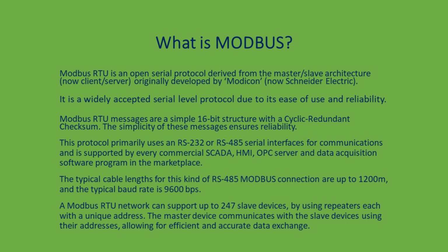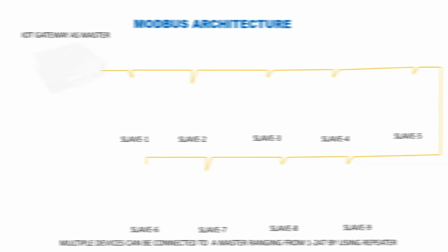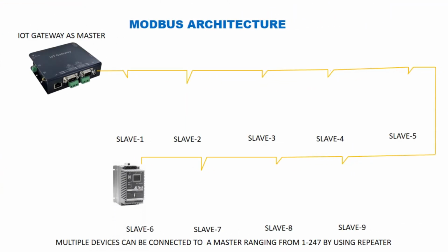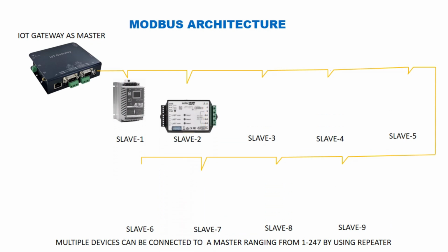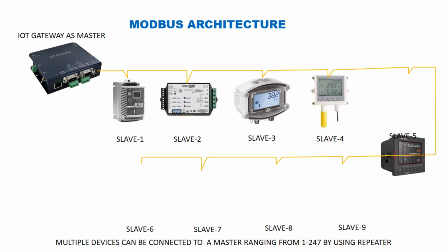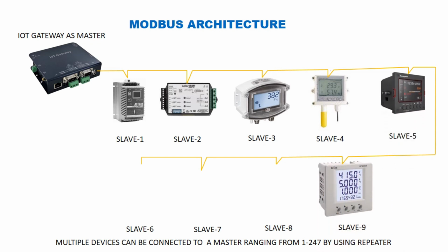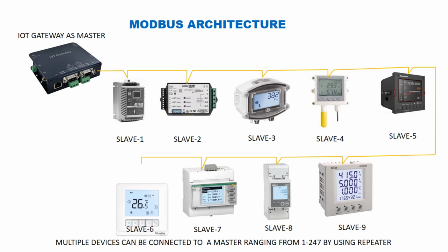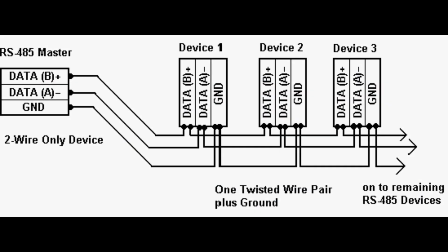Modbus is typically used to transmit signals from instrumentation and control devices back to a main controller or data gathering system. For example, a system that measures temperature and humidity and communicates the results to a computer. Modbus is often used to connect a supervisory computer with a remote terminal unit (RTU) in supervisory control and data acquisition systems. How does it work?